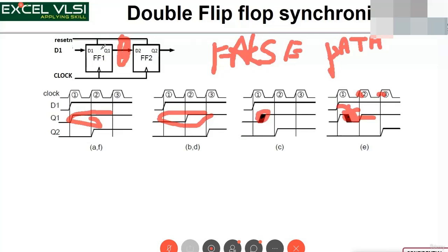And when I am simulating gate level, I turn off the timing checks using my simulator on these flip-flops. If you don't turn them off, what will happen? This will get passed to here when I'm doing simulation as X, and further the whole of this passes again from here to one more flip-flop connected, that also goes X, X, X, X, X. I will not get any predictable output at all. So that's where I turn off the timing checks when you're doing static timing analysis.